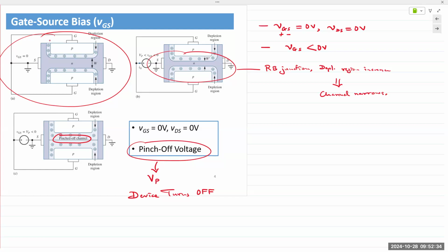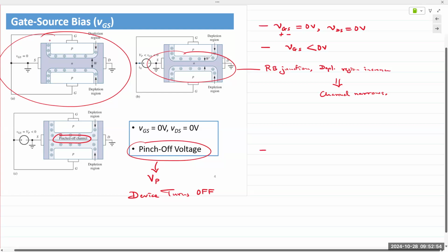A negative voltage must be applied at the gate to turn the device off. So the device is inherently turned on all the time, and since a voltage needs to be applied to turn the device off, it is also known as a depletion mode device.